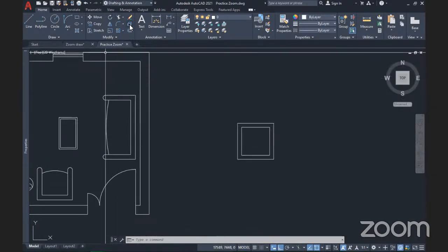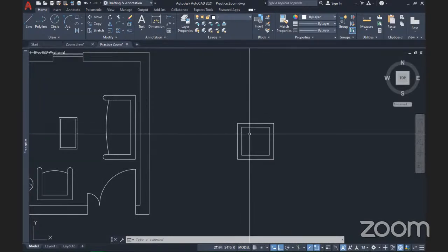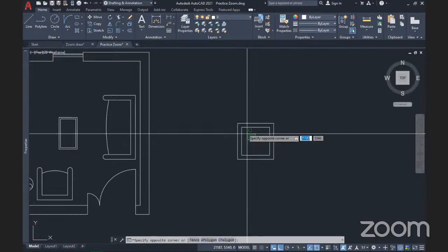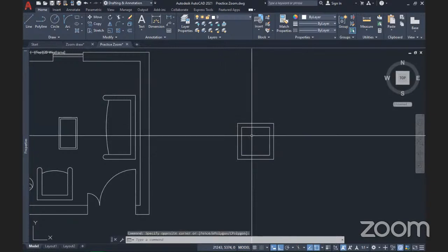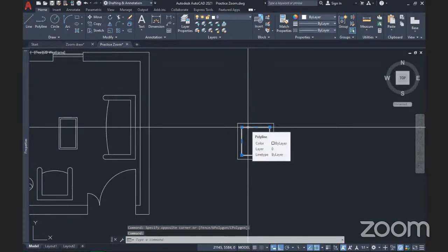So you see this one here, it's called explode. What it does is that it separates all the joint elements or the joint lines to explode them and give us segregated lines. Like, you know, the difference between line and polyline. As this rectangle is, it is being seen as a polyline.